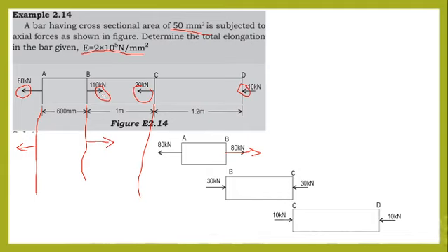So we cannot simply add a force to the system. At the same time, we have to cancel that force. So this is also 80 and this is also 80. So among this, 80 kilonewton is used here. So this is over. So the remaining 80 kilonewton towards left is remaining at this section. Already there is a 110 kilonewton towards right at this section. So the net effect will be 80 towards left and 110 towards right. The remaining 30 kilonewton towards right will be the net effect.